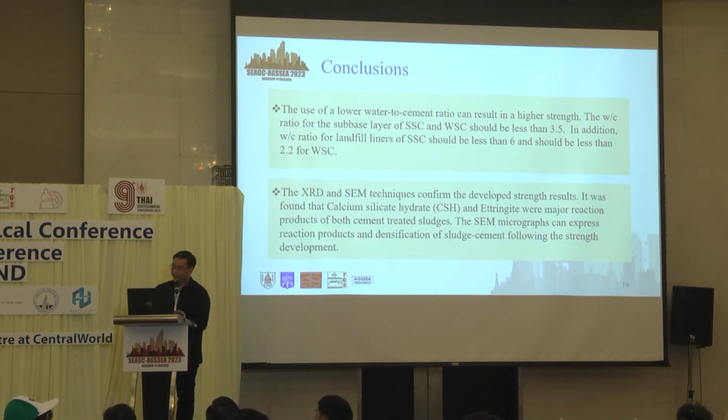The XRD and SEM techniques can confirm the strength development results. The X-ray pattern found that calcium silicate hydrate and ettringite were the major reaction products of the improved sludge. The micrograph can express the reactions, products, and densification of soil cements following the strength development.